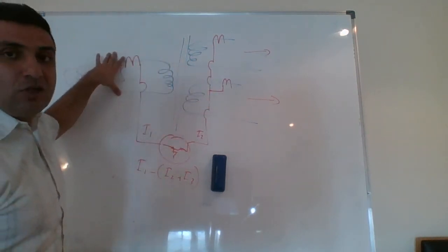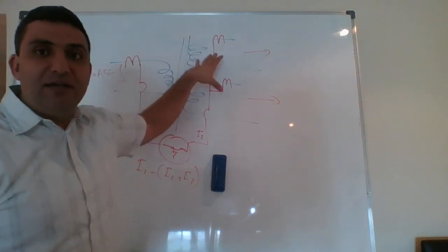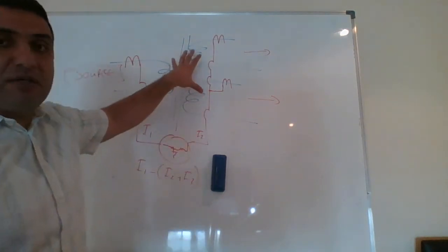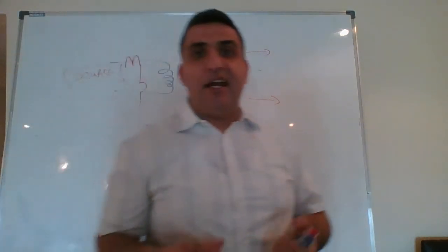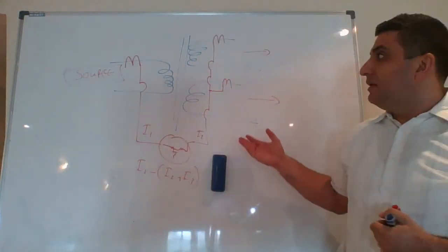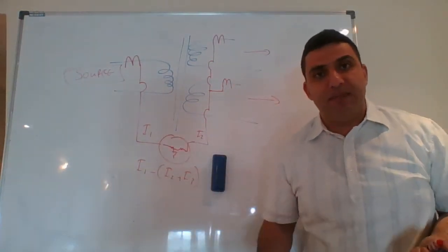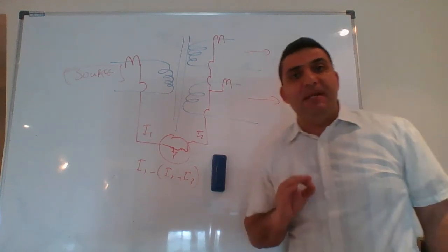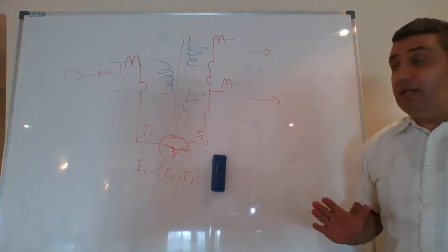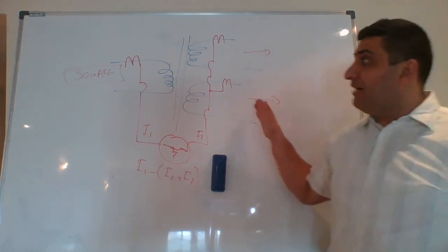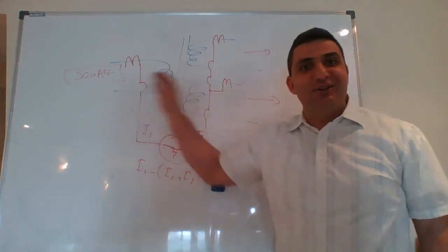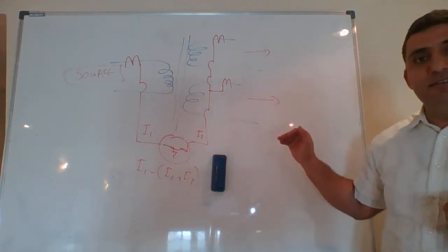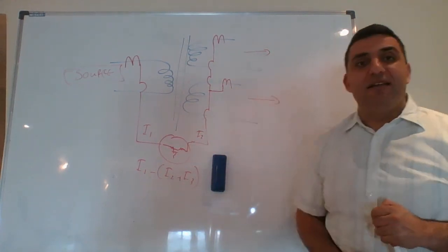The reason is, if this has no input, I can create a fault in here because of the restraint, because of the inrush current, because of a lot of circulating current inside the system. I could have an issue, and I could cause a major problem to my network and a false tripping under certain conditions. What we will do now is take a few minutes break, and then we will solve an example to show why, if I have two possible sources to the transformer, I cannot use this parallel system.